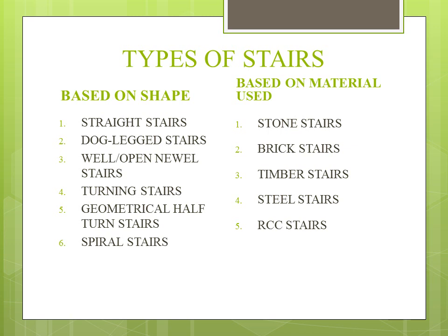Turning stairs, depending upon the availability of space, this type of stairs may turn in various forms. Quarter turn stairs is there, 3/4 turn is there, that is turning stairs. Then geometrical half turn stairs. This type of stair is similar to the well type stair, but the well formed between two adjacent flights is curved. Then the spiral stairs, or they are known as helical stairs, are commonly used as emergency exit.